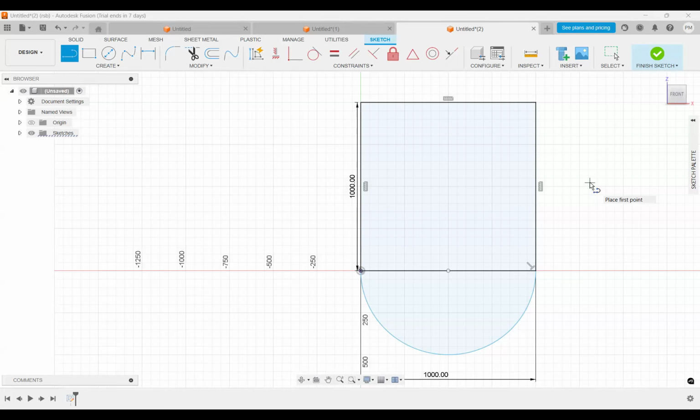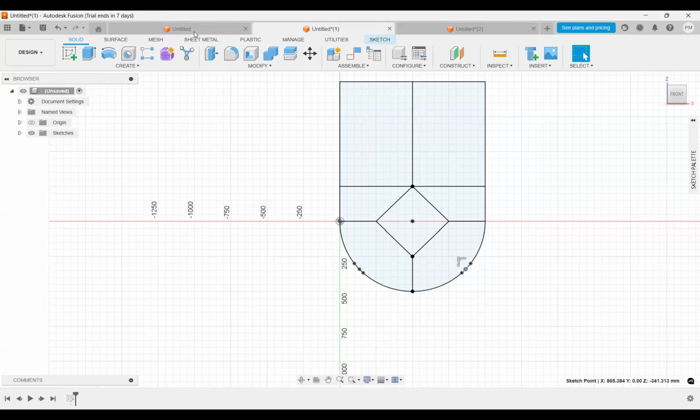If you take this as one block and directly give this much arc in the blockMeshDict, you will find the skewness will be greater than one. So we have to divide the hemisphere into multiple rectangular blocks so that we have minimized arcs. For that I created this. If you have any ideas, you can share, and we can try that as well.